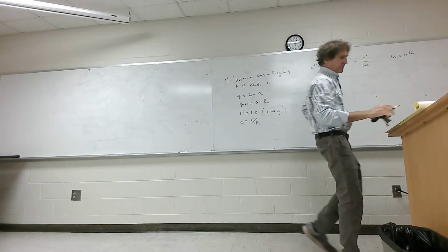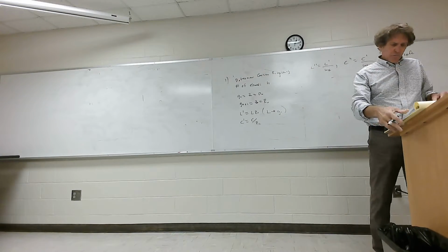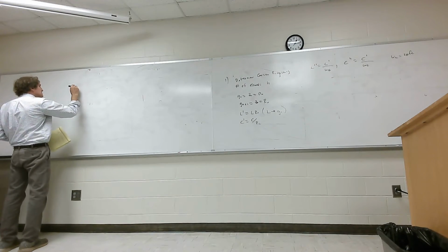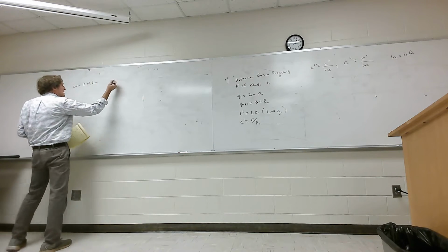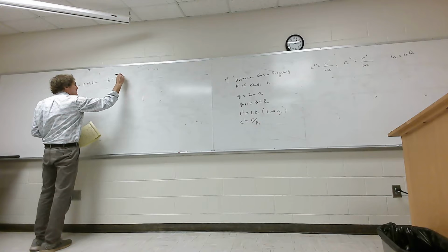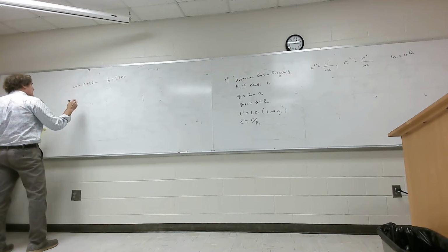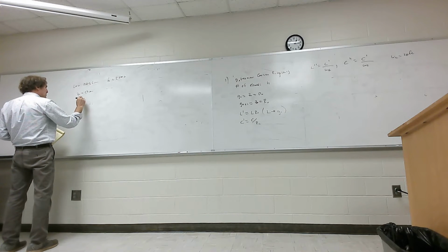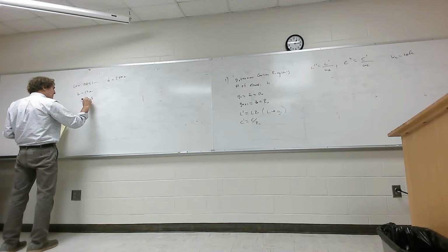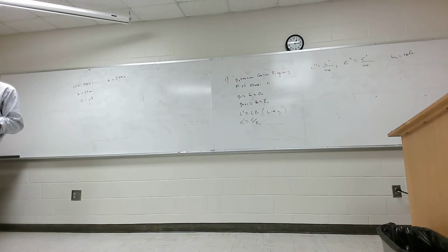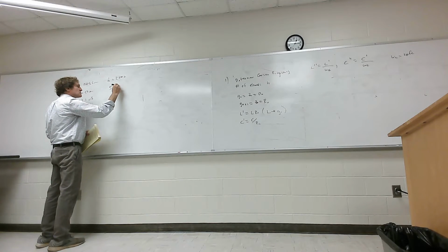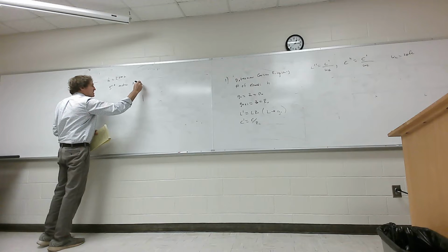the next one is, he wants a low-pass filter with a cutoff frequency of 2 gigahertz. So this is a low pass. Nothing new there. Characteristic impedance equal to 50 ohms. And now he wants 0.1 dB of ripple. That would be in the insertion loss. That's very low, so there's more elements involved too. And it's a third order filter. So write that down. That just means the number of elements is equal to 3.